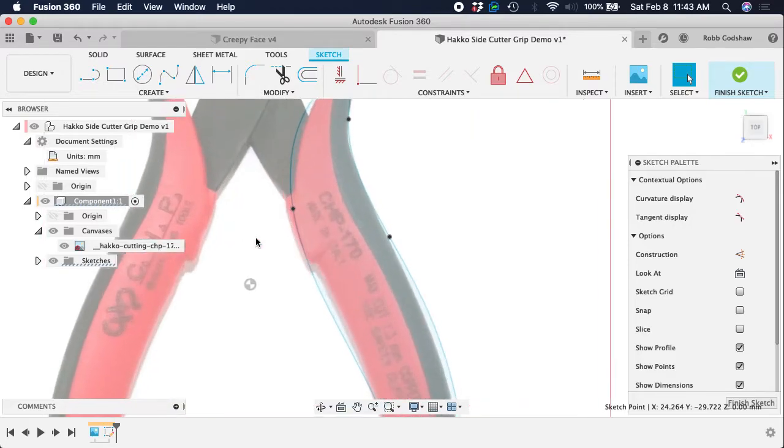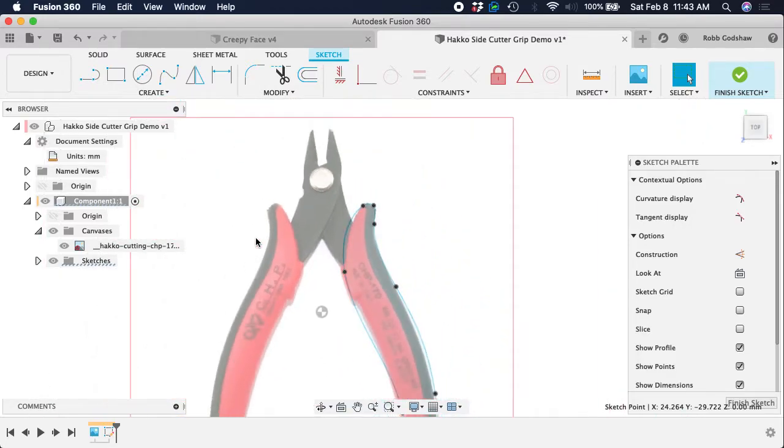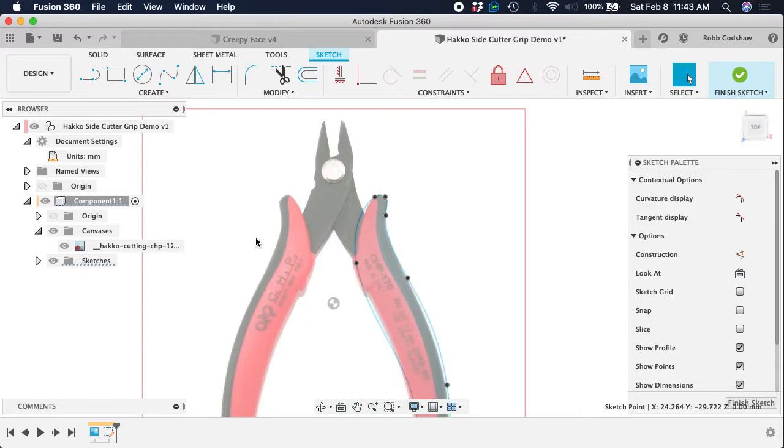And just while we're here, I want to point out that this tool has an insane number of processes. So it has a rivet here. So there's riveting. The basic shape is stamped out of steel. Then that steel, after being stamped, is bent. After being bent, it's ground to be sharp. I think it's then machined so the hole is perfectly round. They then add a spring that's invisible. It's like a coil spring on the other side.